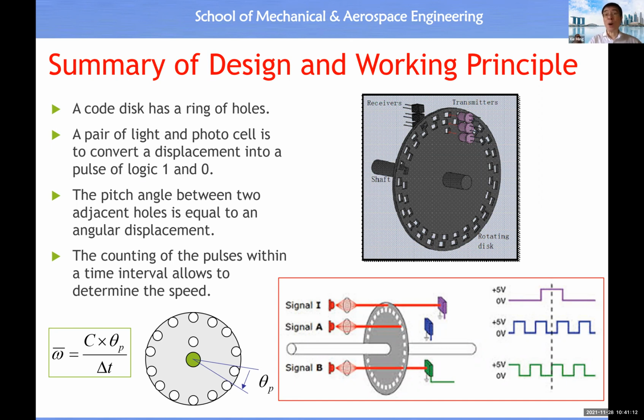to be incorporated inside the power joint. So in order to know the positional information, we must do the homing. Homing means to get this signal, to get this reading. Once we get this reading, then we know we are at the zero position. Because once you power off and then power on, this zero position will be totally lost. So you need to do the homing, then find all the reference positions for all the joints inside your robotic arm. So this is a key element inside the design of a velocity sensor.